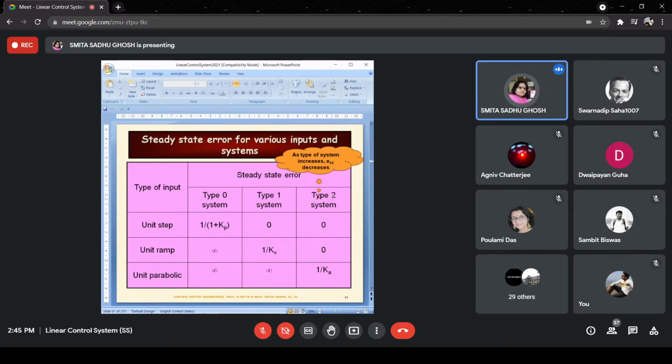So in case the closed loop transfer function is given, you have to actually find out the open loop transfer function considering a unity feedback. And then when you look at that G(s), the open loop transfer function, you can see how many 1 by s's there are. And according to the order over there, you can say what type it is, right?